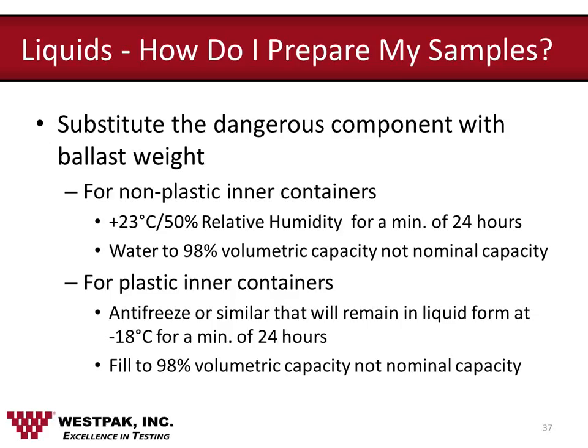Whenever testing with plastic inner containers, antifreeze or something similar is ideal. The reasoning behind this is that the package system is going to experience minus 18 degrees Celsius for a minimum of 24 hours. What this is going to do, if applicable, is make the containers more brittle. It also requires that if it breaks at any point in time, it's easy to see if liquid is coming out of the container.